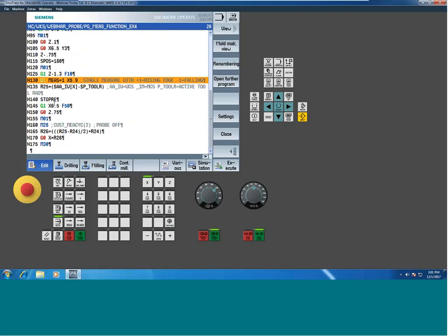Then we come down. We do a little moving. Sometimes you might want to give yourself a stop read. This disables our look ahead temporarily until the machine gets past there. Sometimes the look ahead's too far and it may actually catch a value further down that I didn't want. So sometimes when you get to these measuring things, it's handy to use stop read commands.